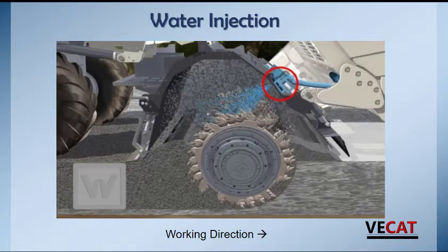And again, we have a shot of the Wirtgen mixing drum injecting moisture directly into the mixing chamber. As shown in some of the previous slides, with the water being sprayed on the surface, that only wets the surface. We don't get our optimum moisture through the complete mixture of the mat. So we end up with dry on the bottom, wet on top, bad compaction, bad density.